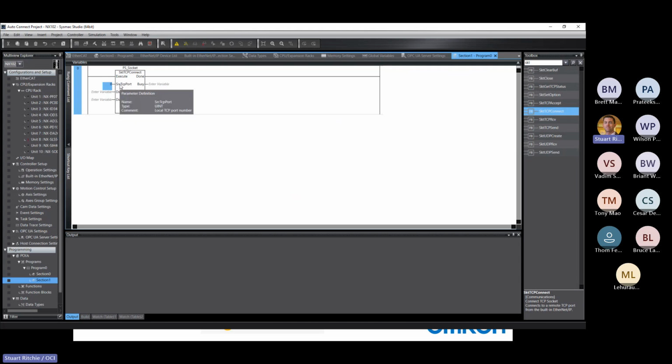If we wanted to specify a port, or if the device we're connecting to required you to connect from a certain port, we could specify that port and use it. But in Modbus, it generally doesn't care. It's the destination port that you need to go to. So the destination address is going to be the IP address of our power supply.